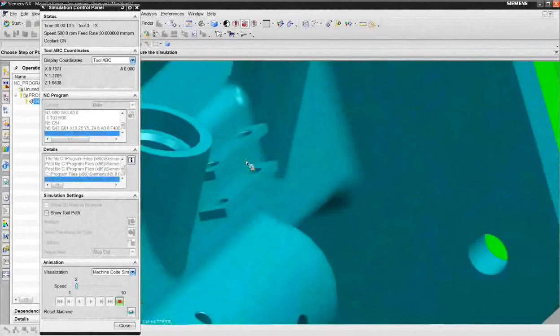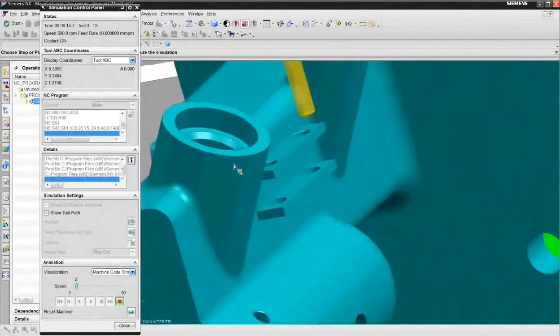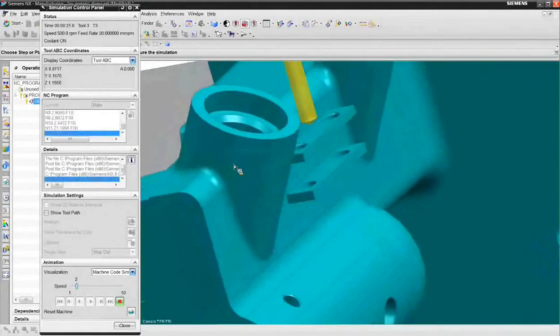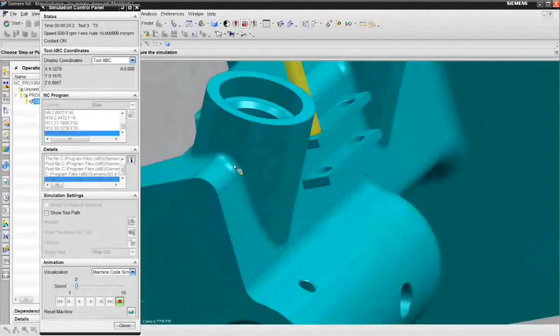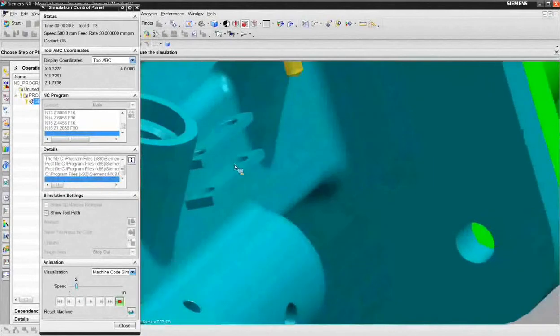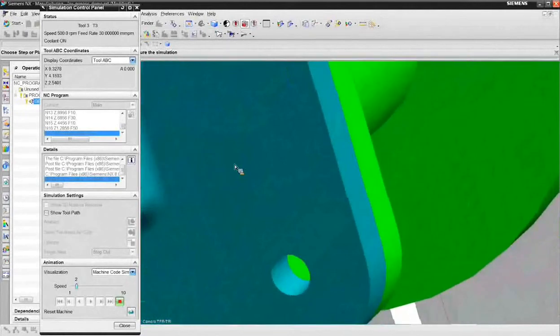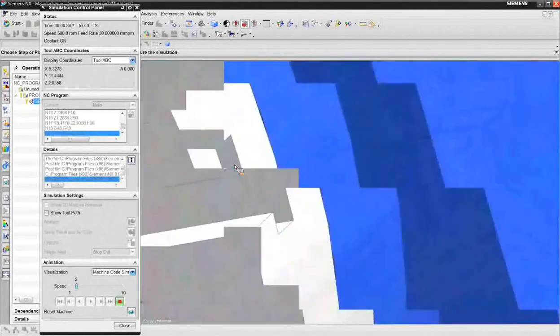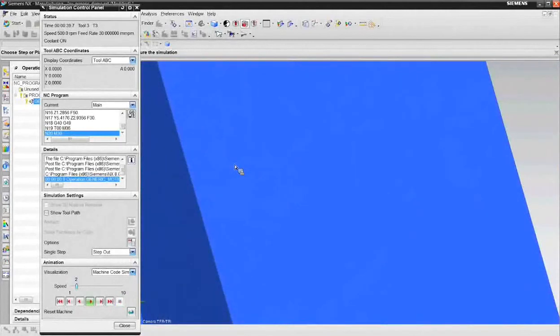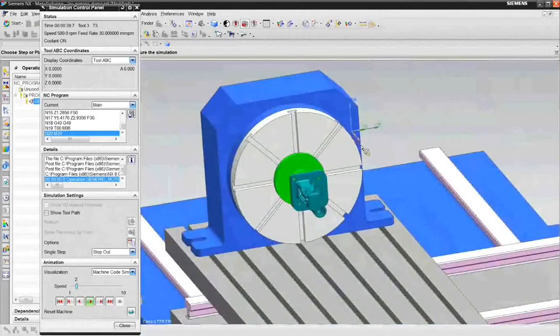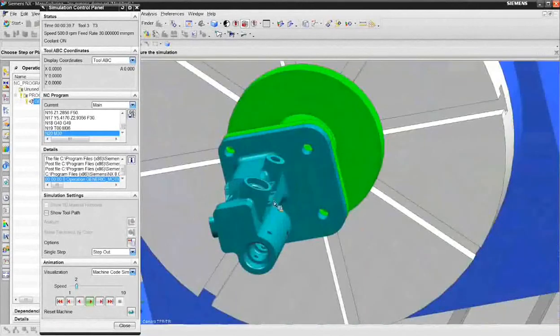Now if you watch the feed rates, the simulated feed rates, so it's going pretty fast, it slows down, speeds up, slows down, comes out pretty quick. You'll actually see the slowdown when you're doing the cutting and the speed up when you're doing the traversals. It's not at the actual feed rates per time and distance that you're seeing that happen, but it's at a relative speed replay, so you can see when you're going faster or slower there, which is kind of nice. So that would be a use of a drilling tool in a deck drilling situation like that. Could come in very handy.